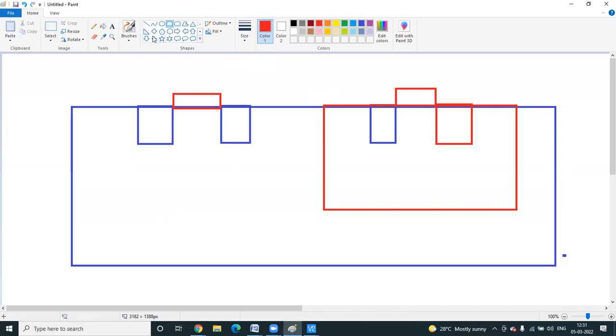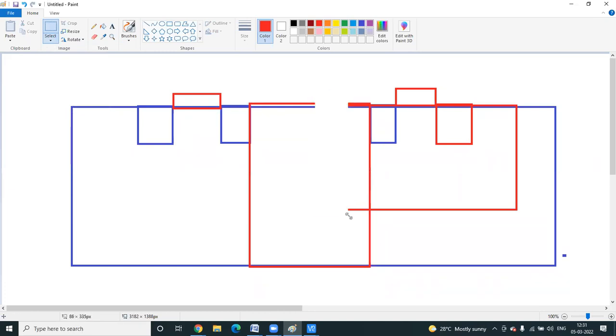So there is a chance of short circuit will occur. So STI means inside this device there will be no substrate, only SiO2 layer. Means SiO2 layer dielectric will be there. Dielectric is like an insulator. If you keep the insulator, the shape will be a little different, not this type. So what will happen? This short circuit current will not flow.